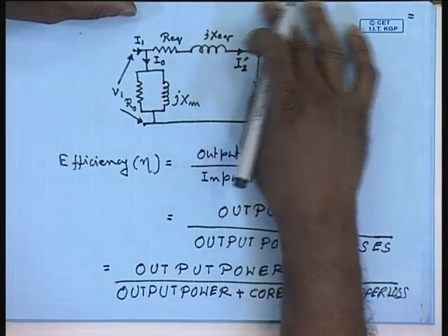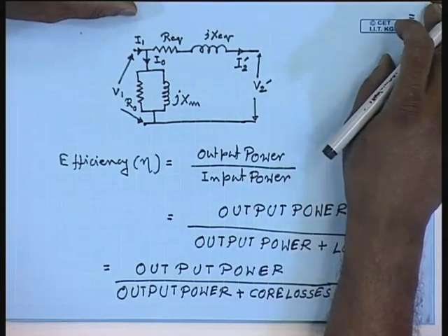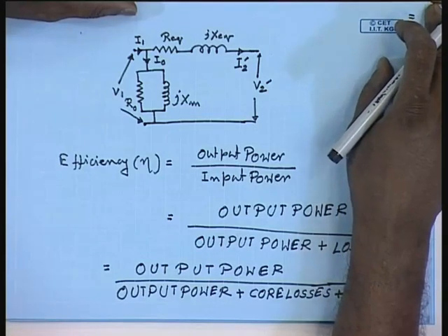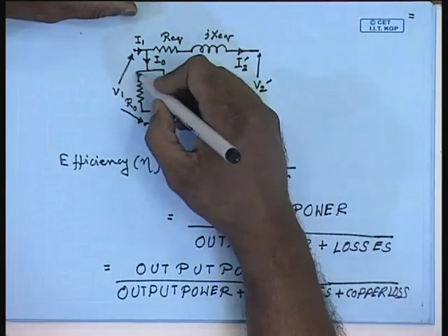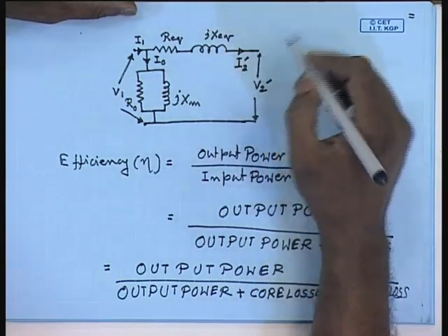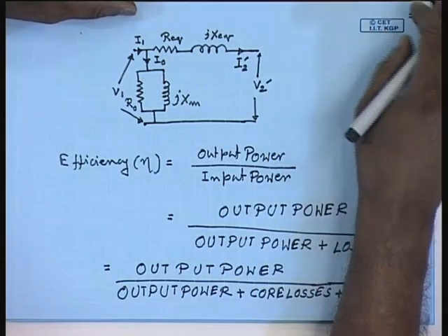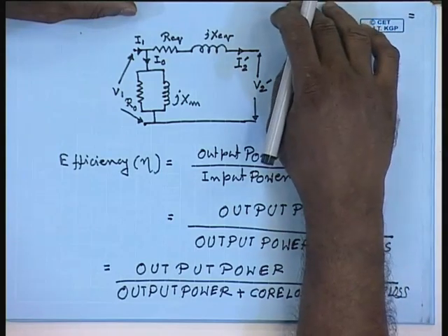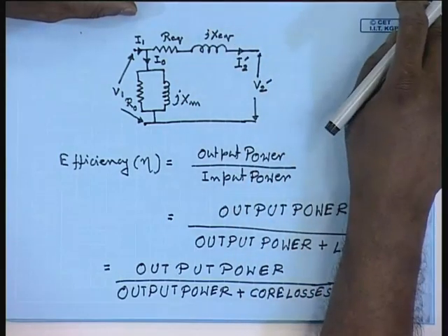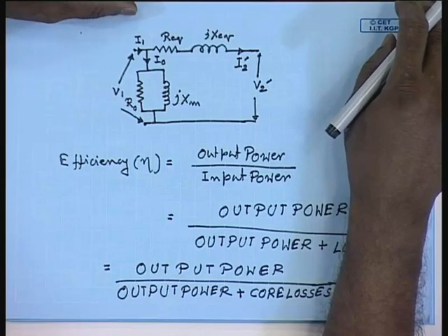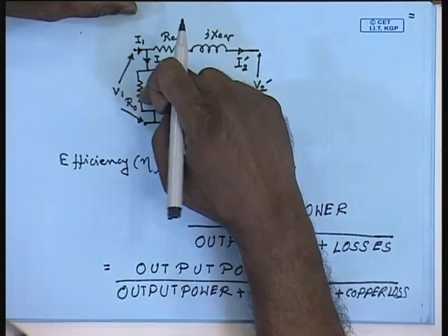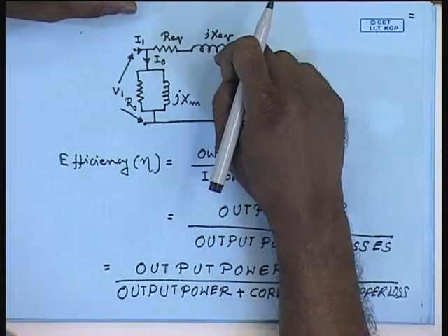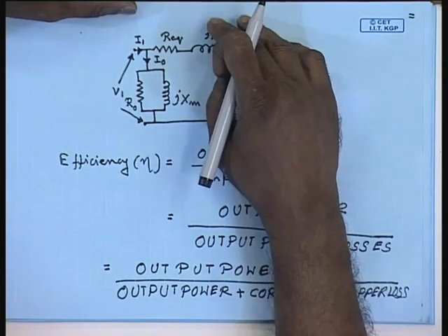We have seen that in the open circuit test, we connect a wattmeter, the wattmeter reading is equal to the core loss, because almost no current is flowing in the transformer, the no load current is very small. Similarly, from the short circuit test data, we argued that the magnetizing current is very small, therefore, the core loss is very small.